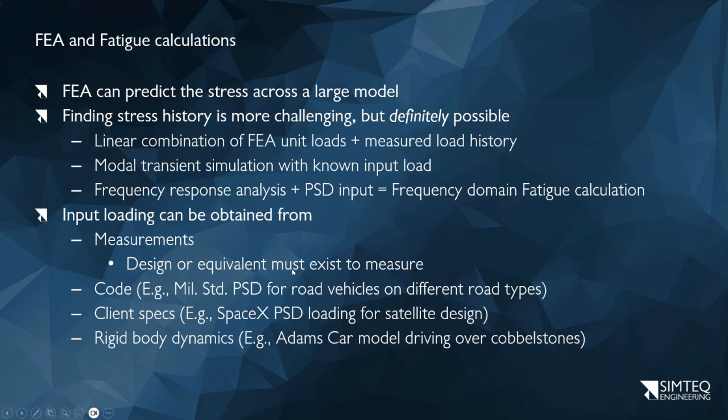An example would be if you measure the accelerations, for argument's sake, on the suspension where it attaches to the rim. So another way of saying is the center of the rim, we're measuring vertical acceleration. If the natural frequency for that suspension was, say, 10 hertz, then you'll see 10 hertz pretty dominantly in the response. That 10 hertz now being the behavior between the road and that point, and to a lesser extent, also from there to the rest of the structure.